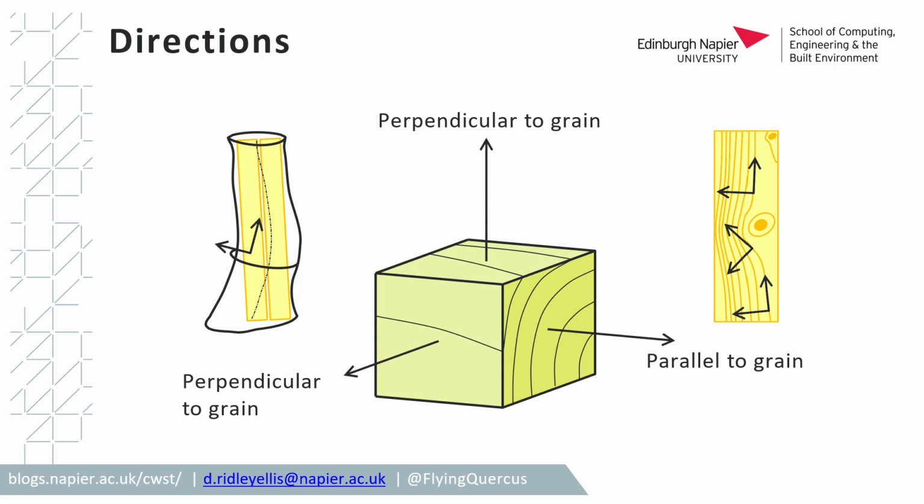So again, the direction of the grain can change depending upon where the knots are. Now, if it's a live knot, that doesn't necessarily mean that it's weaker or stronger than the areas without the knots. If it's a dead knot, then it definitely is.